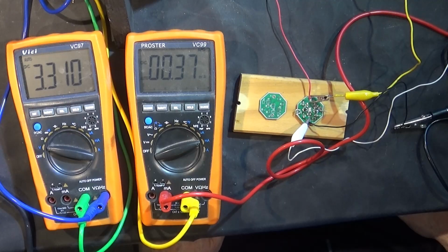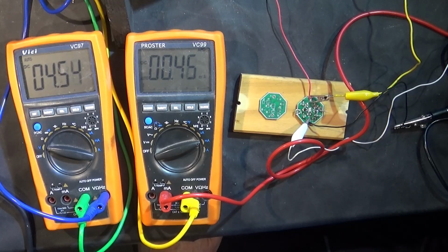So it's not gone up at 3 volts, so we're going to pull the voltage up. Okay, that's just about a trigger, and it is a bit high, but it's still lower than a millivolt, so I will take that. And we turn it on, and it's 17 odd milliamps, that's what the LED is drawing.